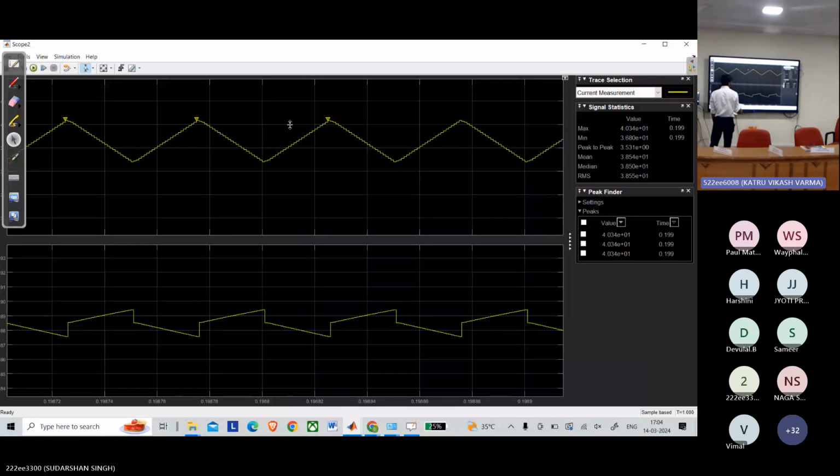So I0 is coming to be around 20.6 ampere. So 20% of that will be more than 4 ampere. As we are using a larger L value, it is satisfying my ripple criteria. Similarly, you can check the delta VC also, get the output ripple, and it is also satisfying.